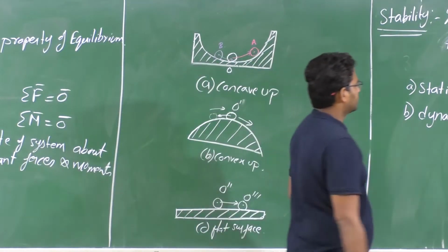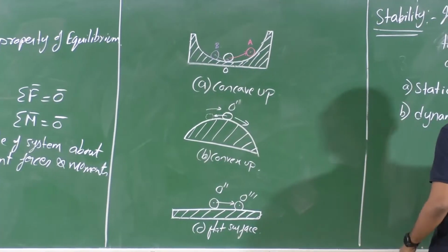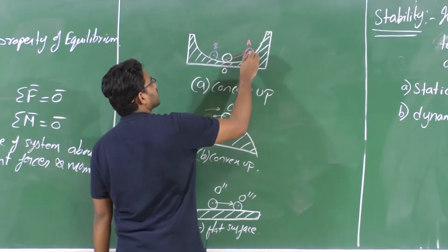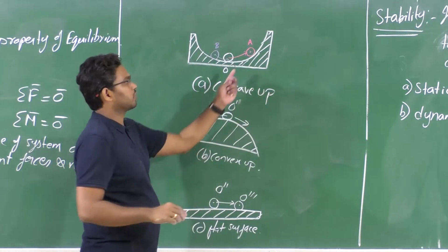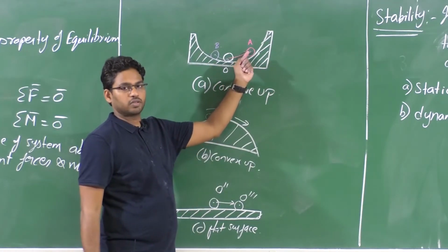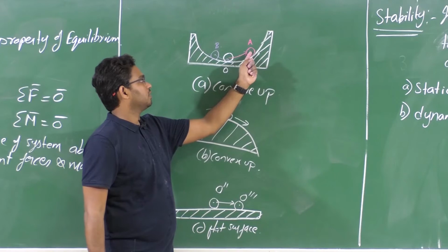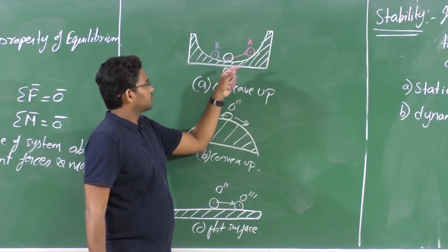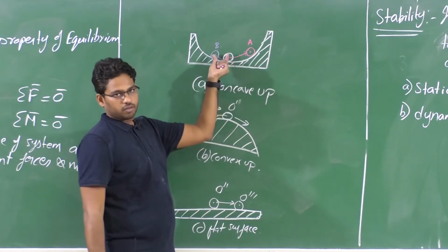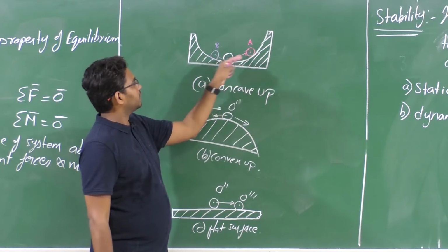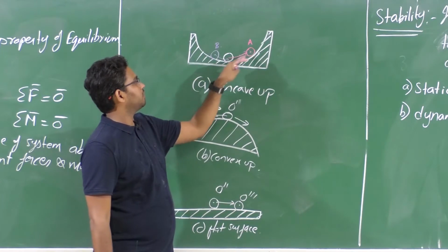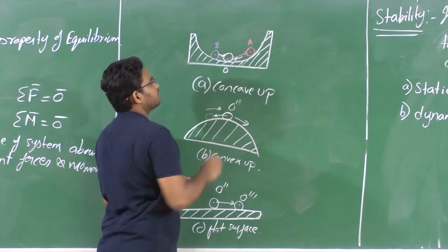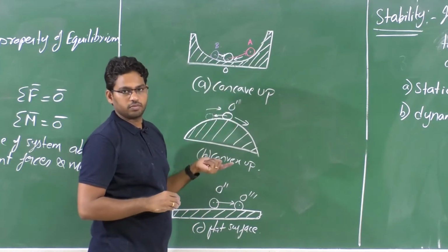Now, what is static stability? Whenever, in this particular example, this ball reaches a maximum or zero velocity location, it will try to return back towards the initial equilibrium point. Whether it stops there or not, we are not worried, but at each of these extreme points, it has a tendency to move back towards the initial equilibrium location, right?